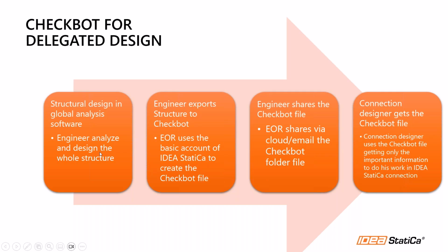So this EOR needs to send information to the connection designer, and normally that's done through maybe detailing plans or drawings or simple sketches or just a simple representation of the model. And also he sends only envelope forces, envelope load combinations. But now with this functionality, the engineer can export the whole structure to Checkbot using a basic account of IDEA StatiCa. Then he or she creates the Checkbot file.